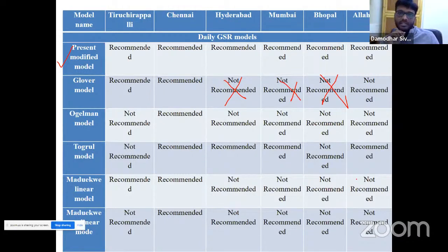Correspondingly, they will suggest the area of the power plant if you want to install that many power plants, and what battery backup we need. For example, based on how many cloudy days there are in that area, the battery sizing will be decided. These are all design analyses before installing the real system in the actual field.